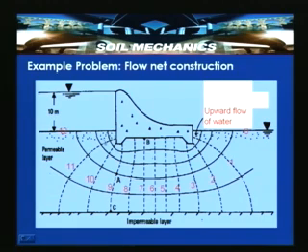So, flow channel 1, flow channel 2, flow channel 3, flow channel 4 and flow channel 5. If you look into it, this being an equipotential line and this being an equipotential line, and this being a flow line, at this junction the orthogonality is again maintained. By maintaining this approximately 90 degrees orthogonality, equipotential line 11 has been constructed, 10 has been constructed. Similarly, you have to ensure that the orthogonality between equipotential lines and flow lines is maintained throughout.